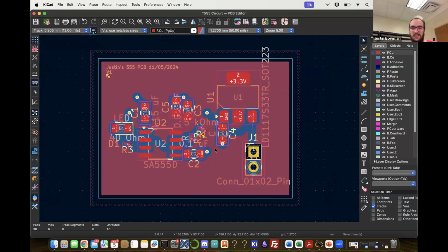And if you only want to move, say, your actual components, you can select just those. For that, you have to press B to get rid of the trace cuts. Pressing B again gets rid of that, and then to get rid of vias, you can press that. So very nice. I'm sure there's tons of tricks and little things in here that I'm not aware of. But yeah, this was great.